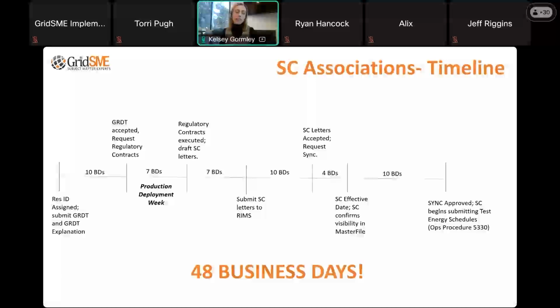We recommend at least 7 business days prior to our target sync date so that the scheduling coordinator can start submitting test energy schedules and they have time to do that. So that's a really important timeline to be aware of: the SC association has to be effective at least 7 business days ahead of time. We just want to make sure we're tracking towards that. Once that SC association is complete and we've got sync approval from CAISO, that SC is responsible for submitting test energy schedules. Talk about that later this afternoon if you want to stick around for our commissioning section.